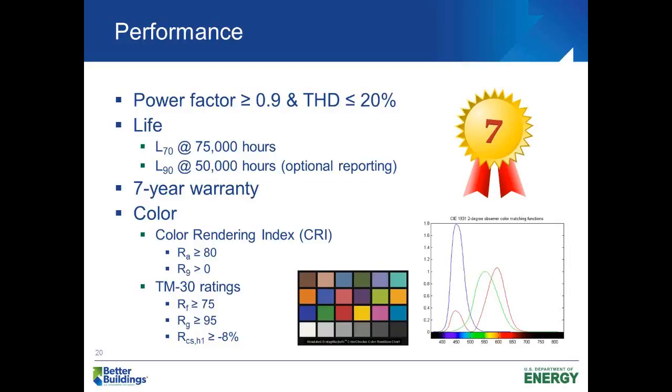Right. So that is an excellent point, Michael. And what I'd like to say here is that while we provide a specific light distribution as a minimum requirement, each particular space has its own individual needs for how that light is distributed. For example, you might have a requirement for uplight. That means a certain percent of light in your typical fluorescent fixture is actually going upward because the fluorescent lamps are omnidirectional.